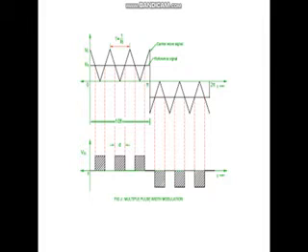The pulse width modulation control methodology is a feedback control. The output voltage of the inverter is always sensed, and if there is any variation, the width of the pulse can be varied. In multiple pulse width modulation, the reference signal is a DC voltage, indicated by a straight line, and the carrier signal is a triangular wave.